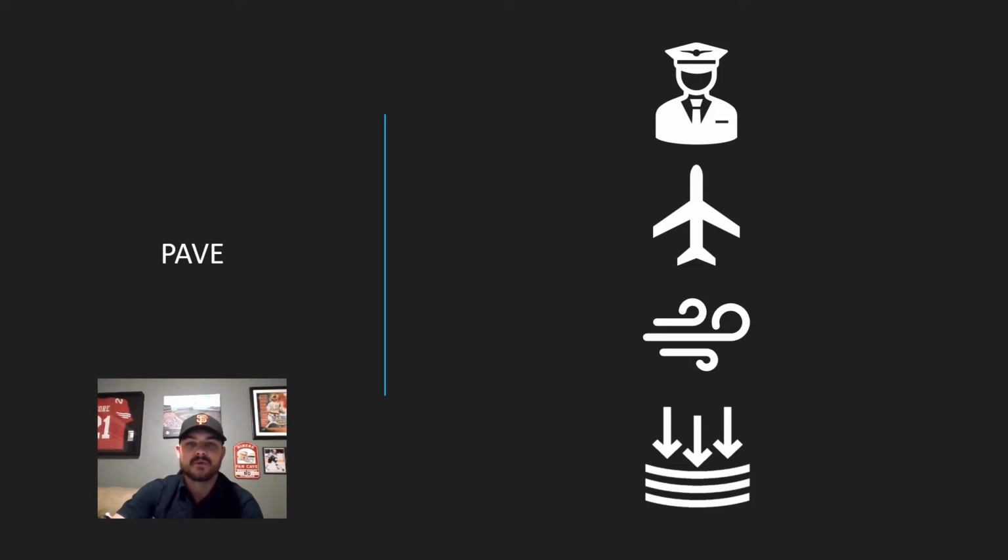V is for environment. We'll consider weather, air traffic control, nav aids, terrain, takeoff and landing areas, and surrounding obstacles. I like to do these flights over the hills just east of Reid-Hillview Airport where my flight school is located. Clouds are often an issue in this area. Although it may be a fairly clear day, the lifting force created by wind flowing over the hills often creates clouds along them. While flying around while maintaining legal cloud clearances or through an IFR flight plan is typically just fine for a cross-country flight, maneuvers require quite a bit of space free of obstruction with plenty of room to see other traffic coming.